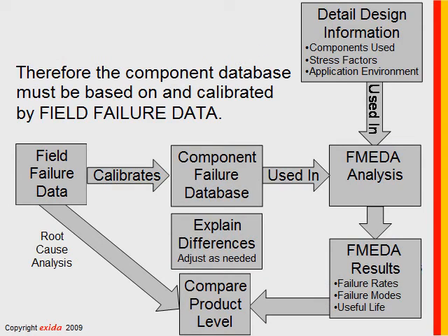Therefore, it's essential that any component database used has to be based on and calibrated by field failure data. So hence, my earlier answer to the question, is FMEDA predictive or is it based on real field data? The answer is both.